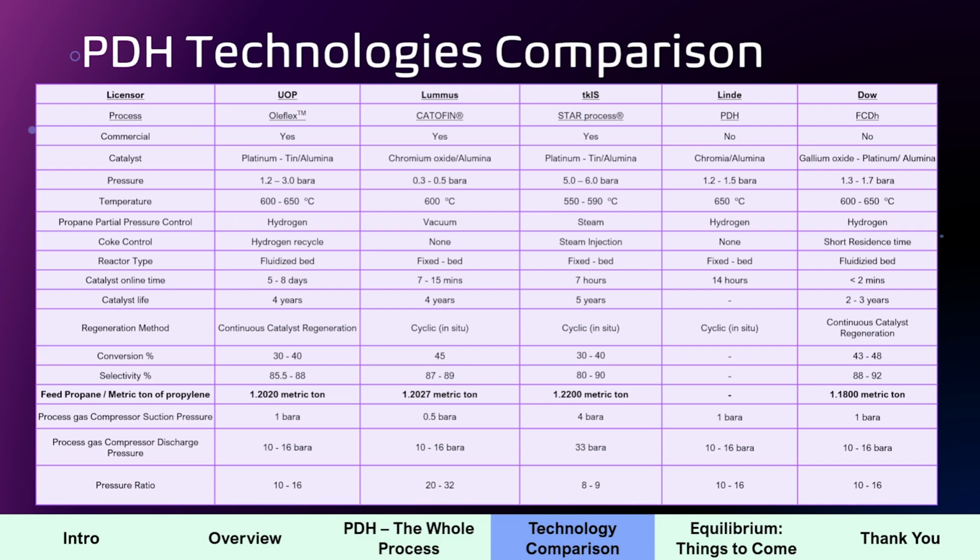But there is a given amount of partial pressure of hydrogen that you need there, that will be retarding the carbon formation. So they are playing this trade-off between how far I can slow down the reaction versus how much I'm slowing the reaction of carbon formation. Which one is being slowed more? So now we're talking about kinetics.